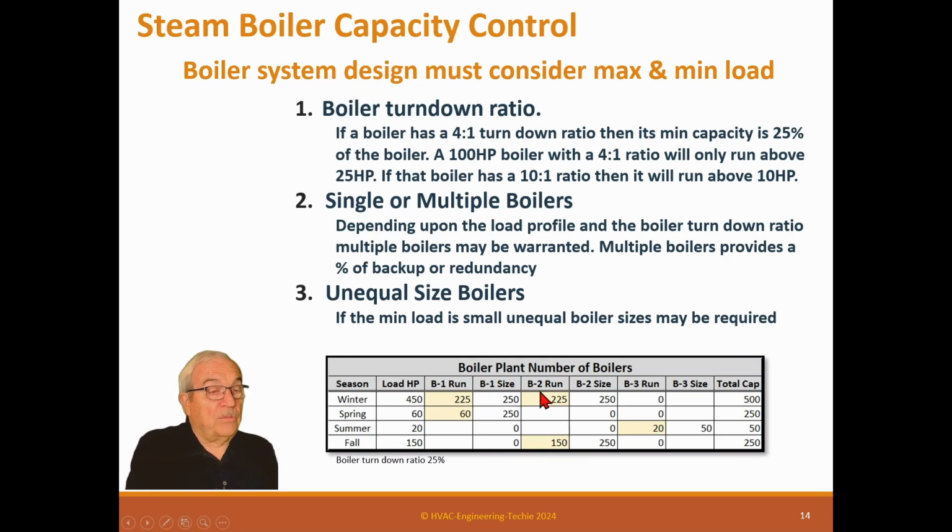This is kind of important when you're considering load, especially in my territory, where we do have steam boilers, but we don't have a lot of load, so the turn-down ratio becomes really important.